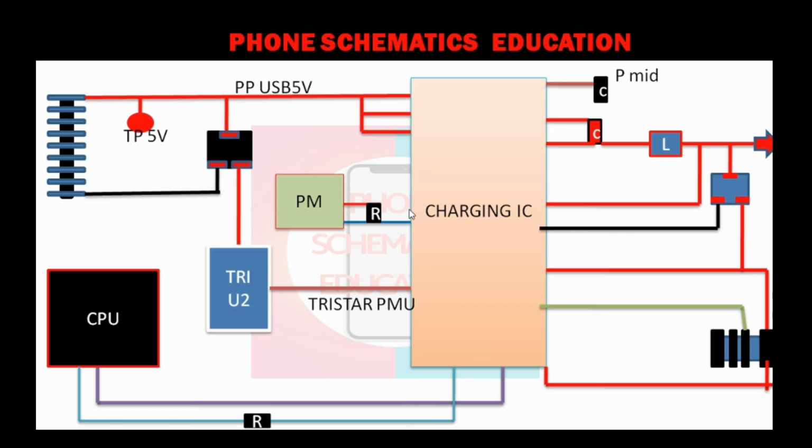Now just a second. Now, a line is connected between the charging IC and the power IC. This blue color line, I have not made a capacitor here, just a resistance, 100k resistance, right? On this resistance you will get 1.8 volt through the power IC, right? Clear? In this line the CPU will know the charging is connected or not, the VBUS charging detection line.